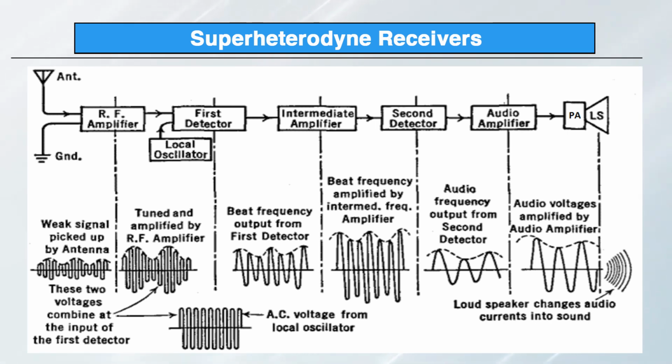The characteristics typically include multiple stages of amplifiers, often using transistors and vacuum tubes to achieve sufficient gain. Each stage may be tuned to a specific frequency or band to maximize selectivity and reject unwanted signals. The design considerations require careful design to ensure stability, gain, linearity and minimal noise figure. It often employs tuned circuits such as LC circuits to select the desired frequency and reject others.